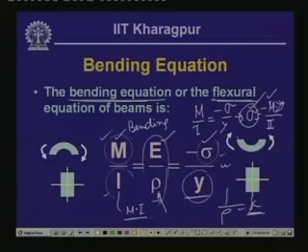to the sectional property. Now, in this particular case when we are dealing with bending, we are again dealing with the sectional properties, but we are computing the moment of inertia about the axis lying in the plane of the cross section. So, now the question is, when we have this bending moment as positive, as we have assumed in this derivation, corresponding to this kind of configuration, then if y is positive, stress is negative. This y is positive when we are talking about the upward direction, this is y and this is z. So, y is positive upward.